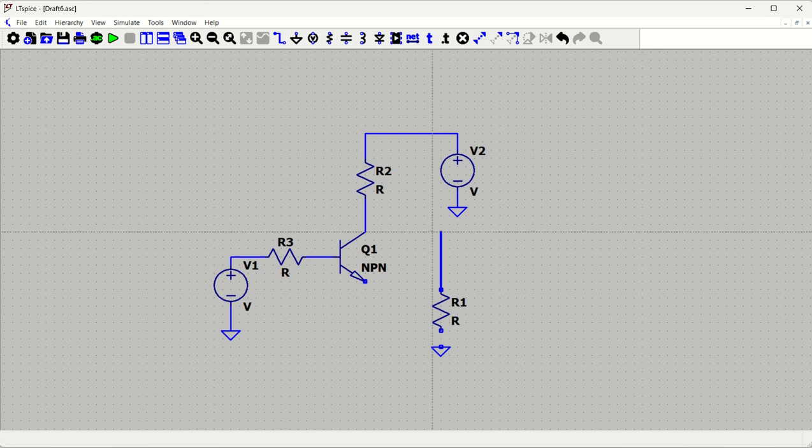And what we can do is, we can take this output at the collector pin. Let's say one more ground will connect at this emitter pin. So this is my emitter, this is my bias base, and this is my collector of the transistor. Now we'll quickly take up some values for all these parts. What you can do is, directly bias this with a current, let's say 30 microampere or 10 microampere, something like that.